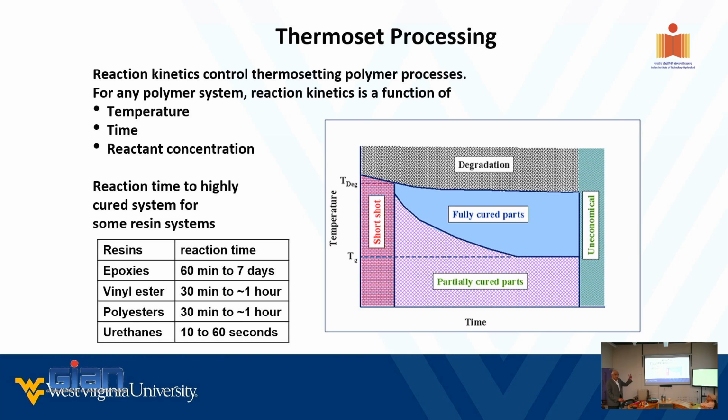But there are high temperature resin systems like polyimides. I can go up to 600 degrees, but they're very expensive. We only use them for specialty applications.